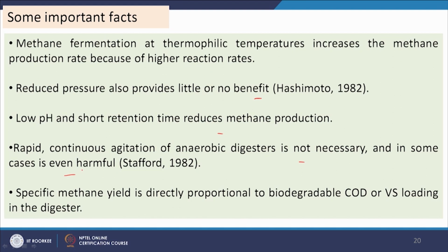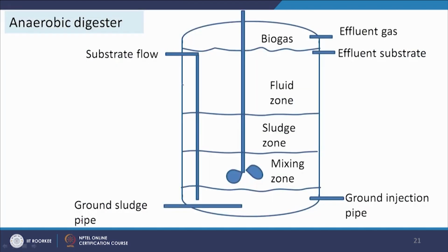in some cases is even harmful. We will see that agitation or slight mixing is needed, but vigorous mixing or agitation is not needed; it reduces the performance of the reactor. And specific methane yield is directly proportional to the biodegradable COD or VS loading in the digester, and if we